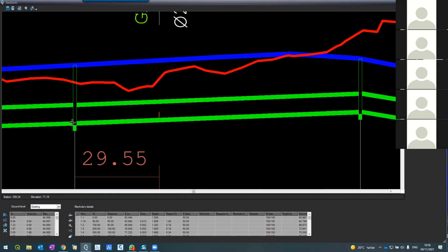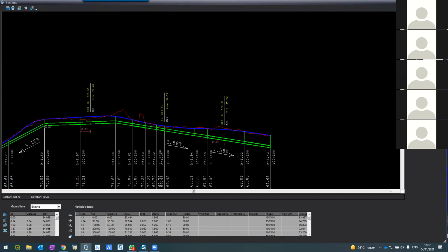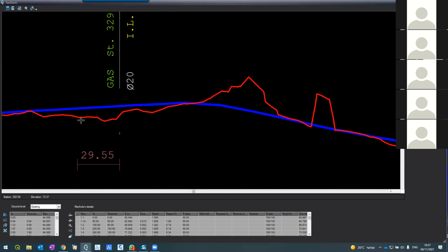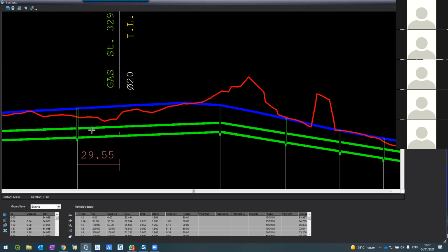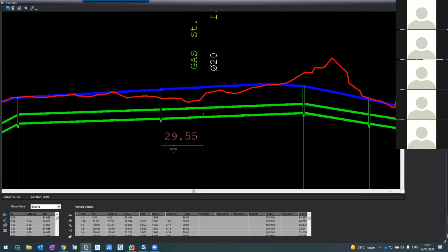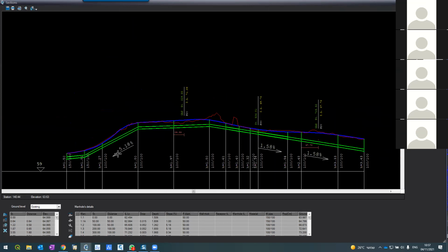So this is the station. This is station 301. No, the drop is not good here. I have to create it. No, I cannot create the drop. Drop will not help me unless I'm going above the pipe. Let's do half a meter above, but then it reflects all of this. No, it's not good.